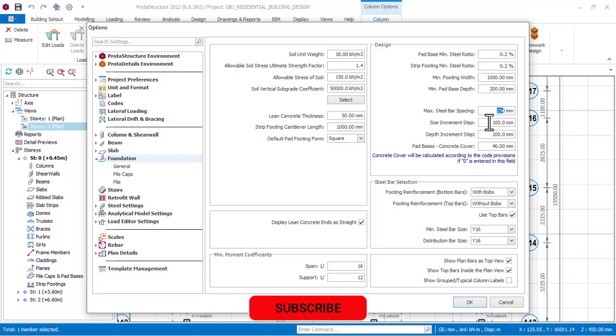Now, for this place that says size increment steps, most software uses 100, but I like to use 50 as my increment. What this means is that if my pad footing is meant to be 1 meter by 1 meter or 2 meter by 2 meter, and at 1 meter there is a failure of the foundation, let me say the size was not sufficient, if you want to increase, instead of it to just increase to 1.1, let it try 1.050.